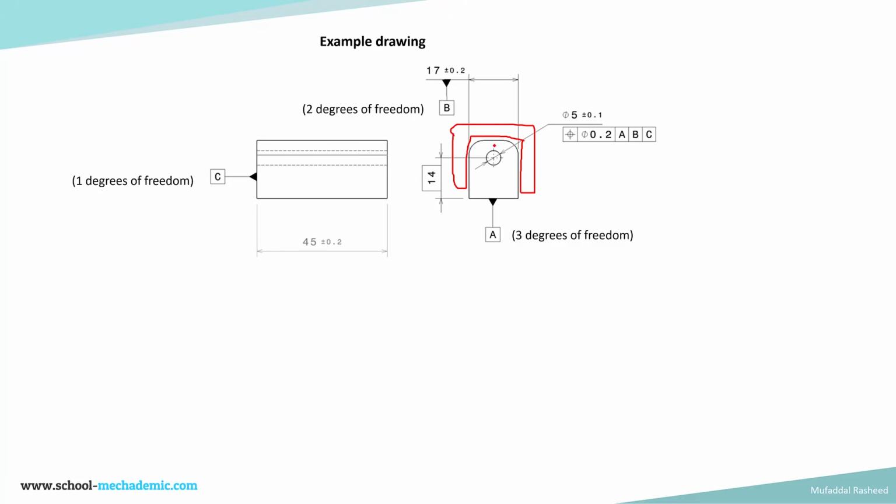This will be a gauge block which will come into contact with respect to datum feature A, and that will of course be variable based on this width. And then this C will be brought into contact with a block over here, the end block. So this is the datum feature simulator for A, for B, and this is for C. This way the 3-2-1 principle is being applied, and then the position of this hole is being checked.